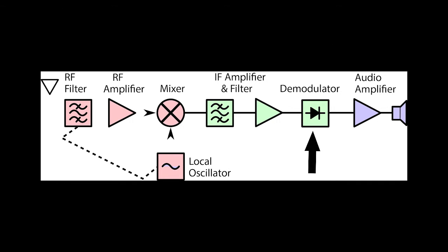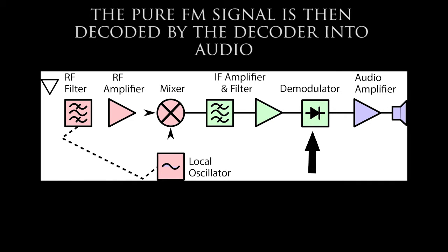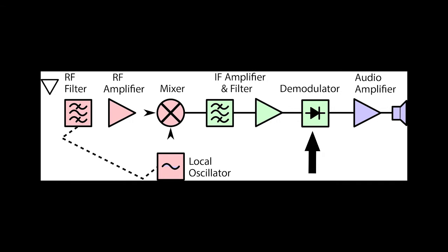Next comes the demodulator or detector stage. Demodulation is extracting the original information bearing signal from a modulated carrier wave. After getting filtered from the IF stage, the received signal needs to be demodulated to harness the information from it. Different demodulators are required for different types of transmission. The basic FM detector senses the frequency variations to extract the information, that is, audio in the case of a radio. It should also be insensitive to amplitude variations to prevent the addition of noise.